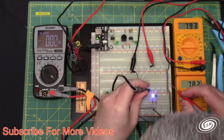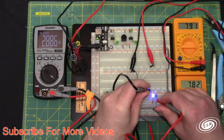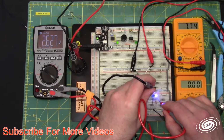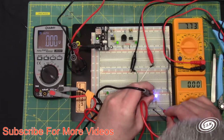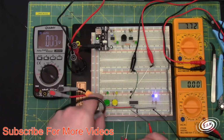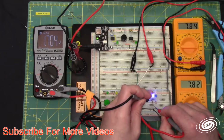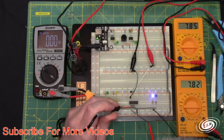Let's check that out. So this one is drawing a forward voltage of 2.88, and if we reset it, what is this one drawing? So 2.89, they have about the same forward voltage. What's the drop across the resistor? Resistor's dropping 1.68. I would expect the resistance to drop the same, 1.68. 1.7. And if you did the math, you would get the 7.8 milliamps.